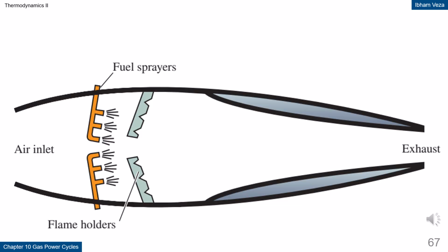Ramjet concept. This part serves as an introduction to the concept of a jet engine without a compressor and turbine. The main idea is to use the aircraft's flight speed to compress the incoming air. By eliminating rotating components, the design becomes simpler. However, this engine can only operate effectively at high speeds. This prepares the ground for understanding the working principle of the ramjet.